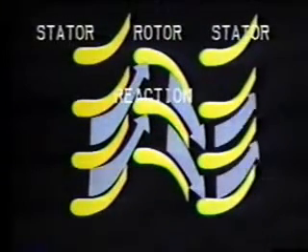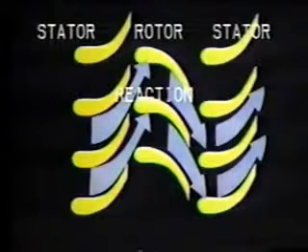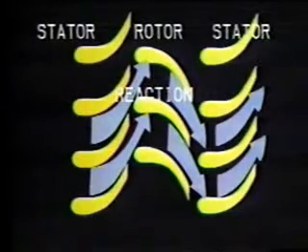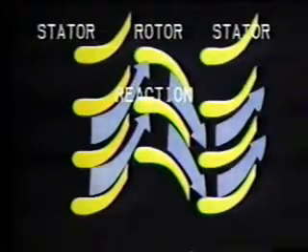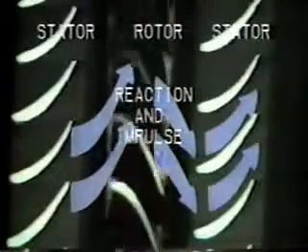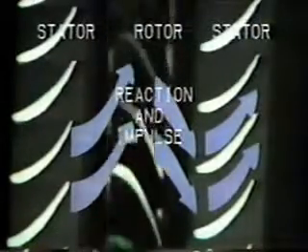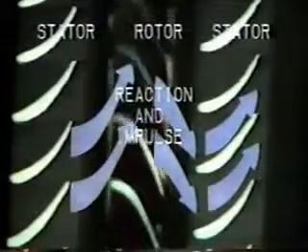This high-velocity air is used in 2 ways in turning the rotor blades. The first is by impulse. Air is directed towards the blades, forcing them to turn away from the nozzle, turning the turbine shaft. The second is by reaction. High-velocity air expands as it passes through the rotor blades, pushing the blades in an opposite direction, again turning the turbine shaft. The Centaur turbine uses air in both ways, impulse and reaction.